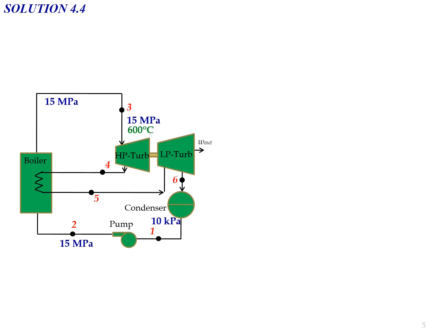The value of P2 we obtain because the question already gives you the value of the inlet of the high pressure turbine in terms of pressure and also temperature, which is equal to 15 megapascal and 600 degrees Celsius. So automatically, for the ideal case, P2 also will be equal to 15 megapascal. For the reheater, for the ideal reheating process, P4 will be equal to P5, equal to P reheat, the pressure during the reheating process.